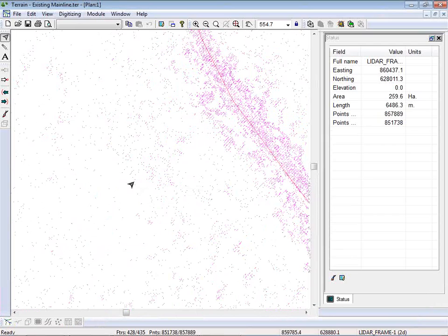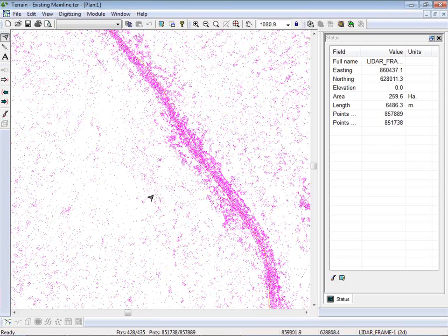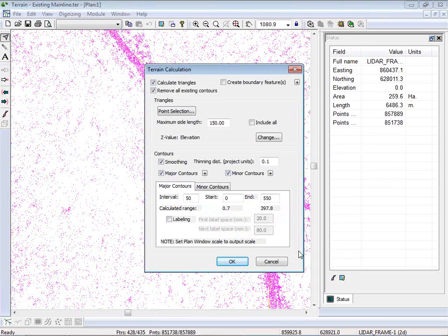So people may tell you that you're getting LiDAR data that's 1 point per meter squared. Depends on the foliage. And watch out, because sometimes you're going to get a LiDAR file from a provider that actually looks like a grid. The points are sitting on 1 meter even spacing. What they've done is they've made a surface, which I can do here very quickly, and they've just laid a grid over top of it and sampled the surface.